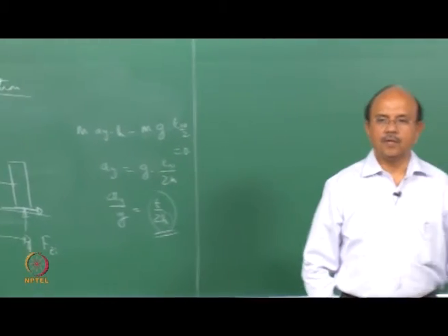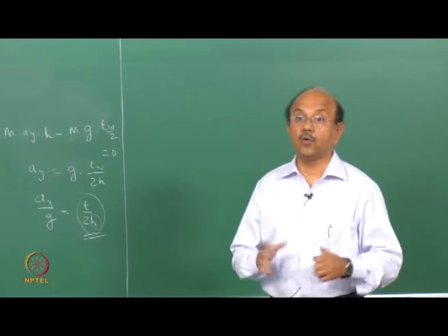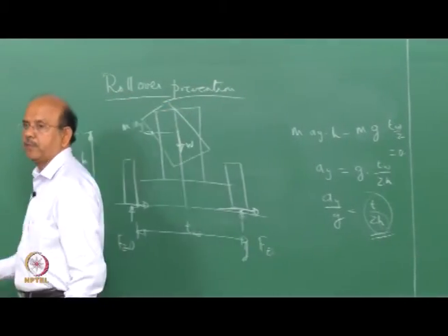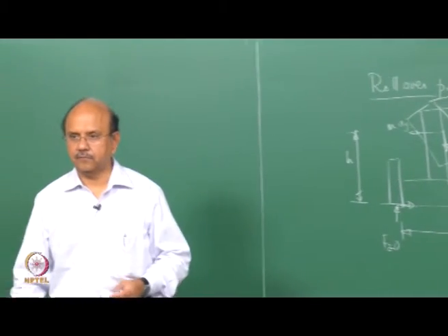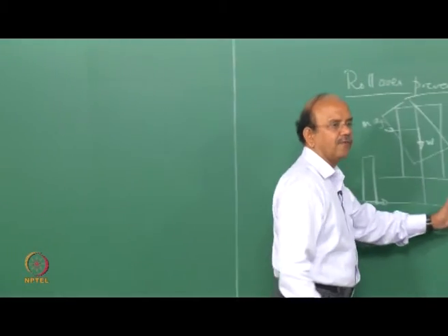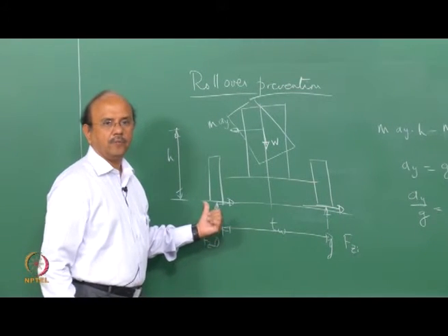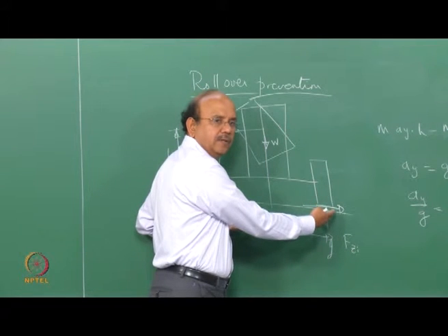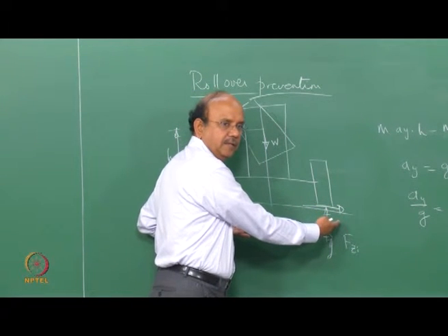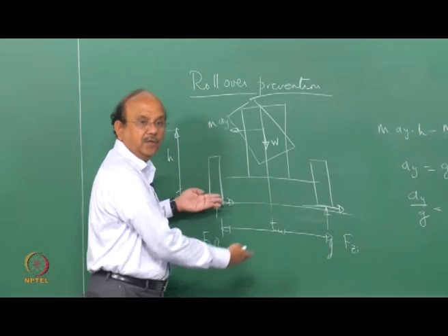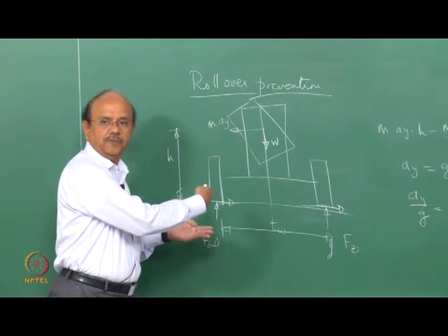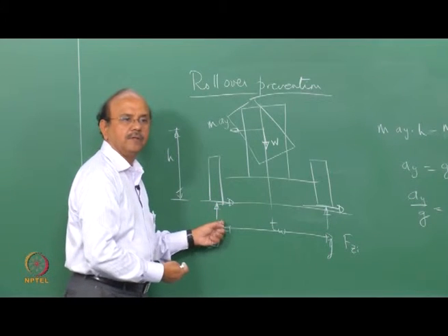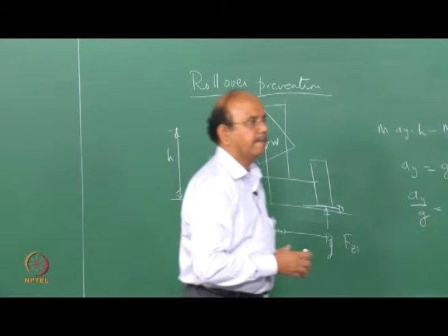Okay. The other factor, and the roll is also, this is one of them, the roll is also due to the stiffness of the tire. The tire stiffness is also going to have an effect. Okay? In other words, you can imagine that Fz in the inner is going to go to 0. The whole of Fz, that is the normal force, will be transferred to this tire.